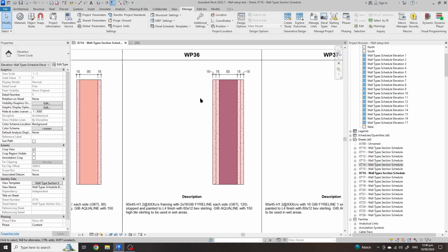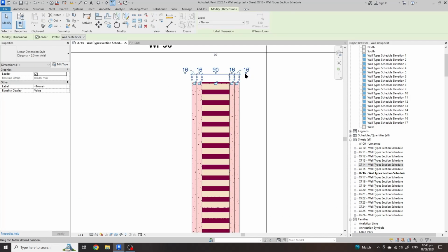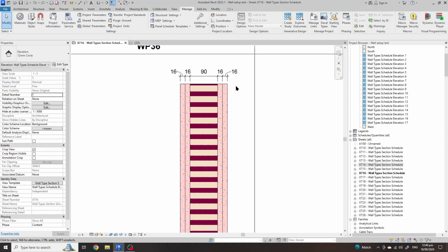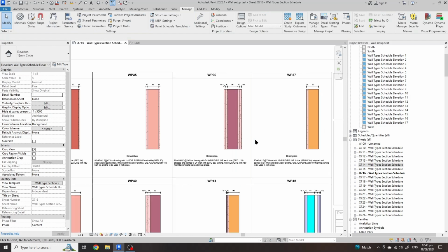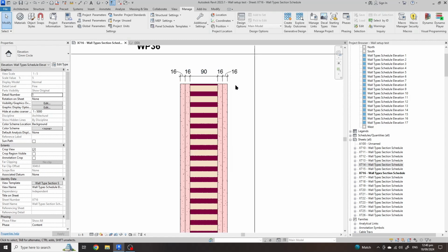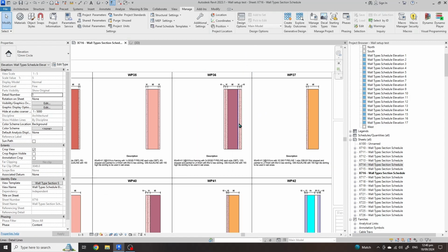So this places the walls. You would still need to put in your detail items over the wall and tag them off to the left here. It dimensions them, and if the dimension is overlapping the other one on the outside, it'll pull it out to the side for you. I also just need to note it draws detail lines over the wall layers to dimension to. So if your wall thickness does change, be wary of that. It's really difficult to dimension to wall geometry in Dynamo.